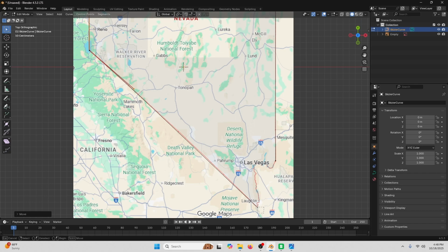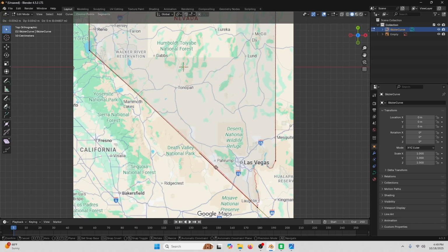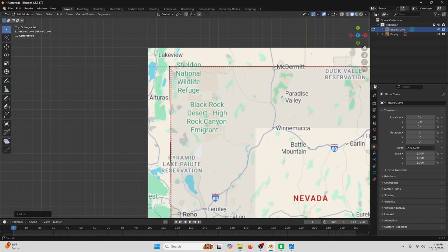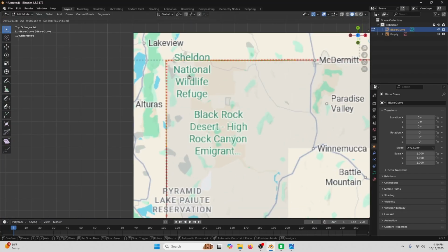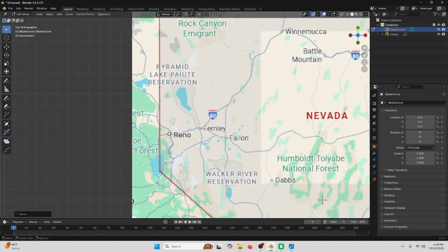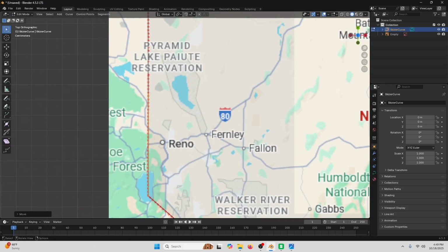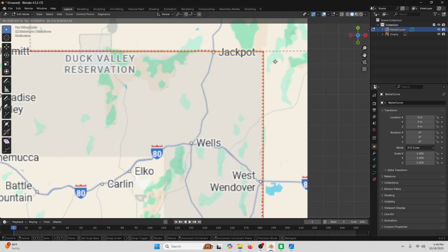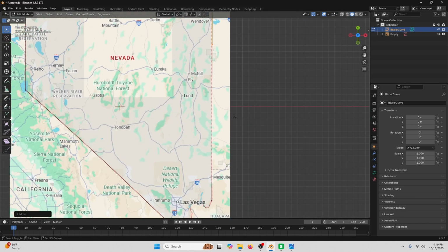And then I'm going to use the control point from this lower right Bezier. So I select the Bezier point, then select this control point, and I now have the Bezier pretty well aligned with the state line. That's pretty much good enough. I'll go around and correct these other points really quick, pressing G to move, select, press G to move, up here, select, and then press G to move and click to place.